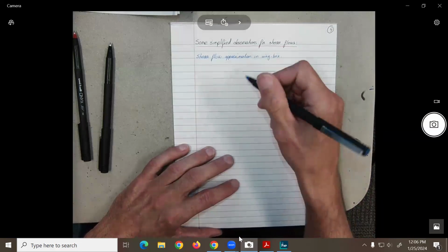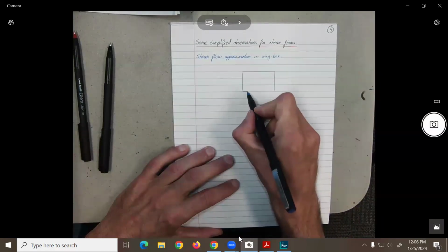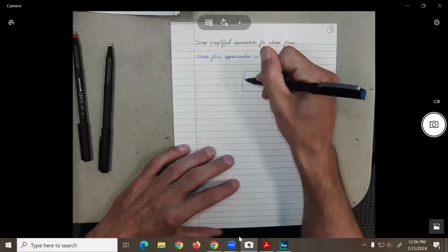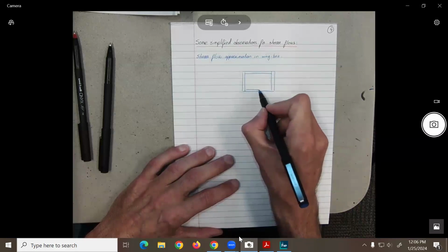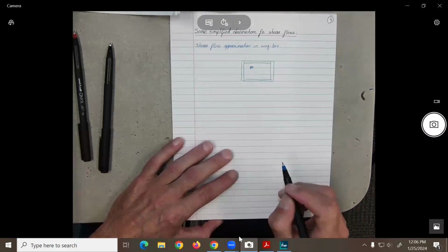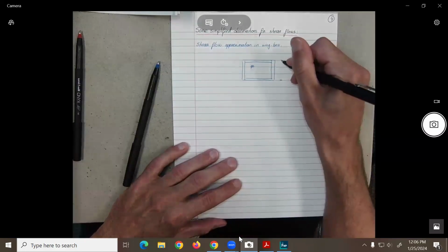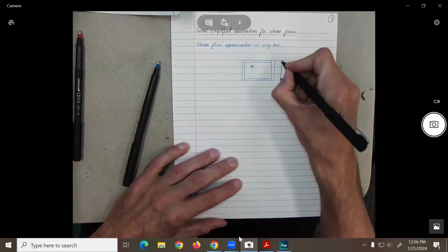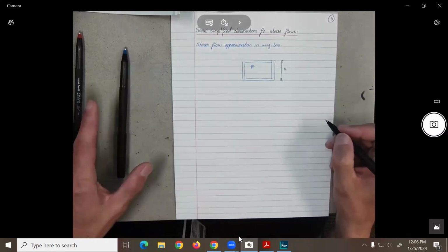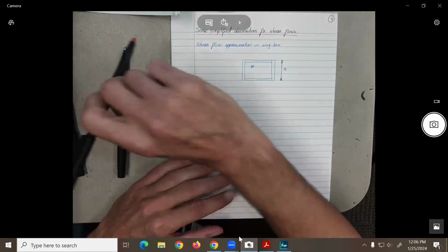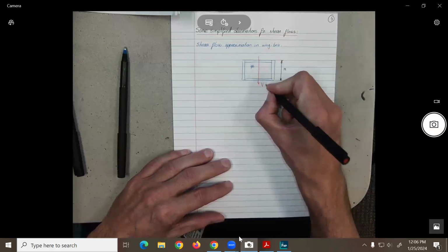Let's say you have a wing box. Let's say you put 4 elements, you weld them together. Here you have a panel, okay? And let's say the depth of the panel, they don't really talk about height in aerospace structures, they talk about the depth of the panel. Let's say it's H, but let's say here there's a shear force V. This is the shear force.